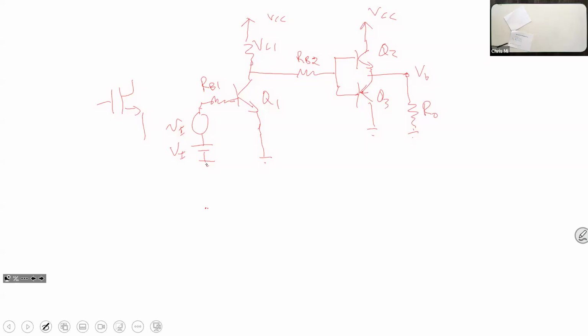When we do this multiple voltage source circuit, especially when they're in series, one effective method is to use superposition. You superpose two voltage sources, because it's a linear circuit. With one voltage you get the output, and then with the other voltage you get another output, and you add the two. That's your output.